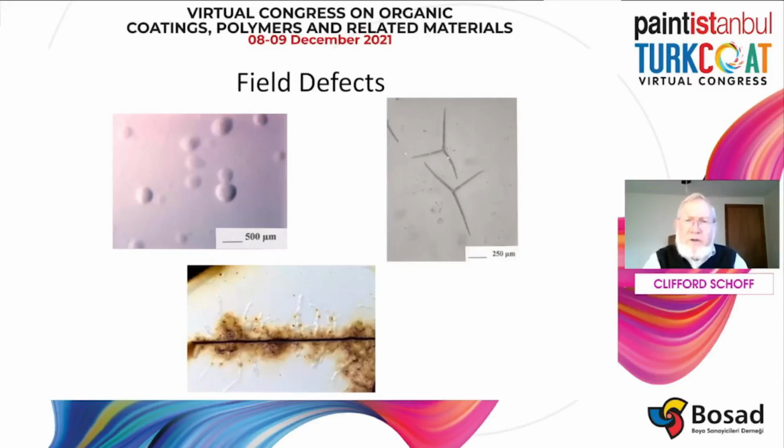You often get the sort of three-corner cracks, and then at the bottom is corrosion, and the little worm tracks that are coming up from the corroded area, the joint there, are what we call filiform corrosion. And that's an interesting process and defect in itself.